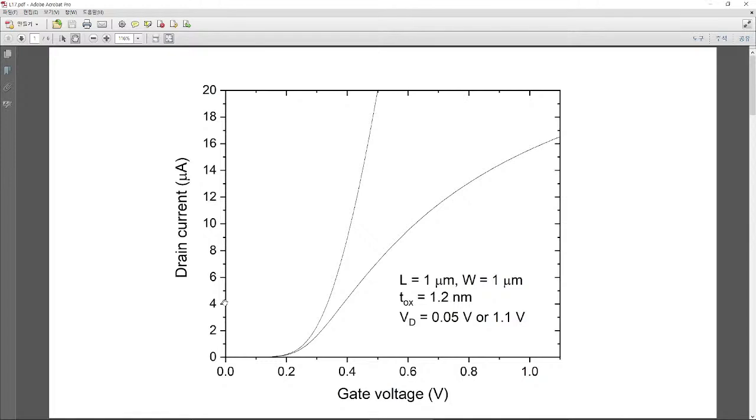This means that our MOSFET does not collect enough electrons. Since when your gate bias voltage is beyond the threshold voltage, now this system really works as a capacitor, so your charge is really linearly increasing. However, still you can observe a severe reduction.